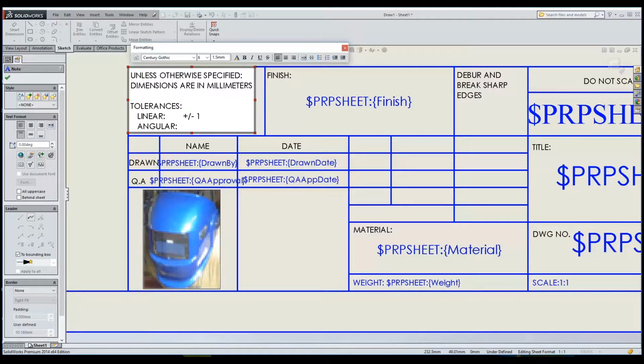Tolerance isn't all that important. We can get away with plus or minus a millimetre and plus or minus a degree in most cases, and I can specify those cases where we need tighter tolerances on the drawing. Let's just put in some default values that work for me. I can alter them on a drawing by drawing basis as needs be.